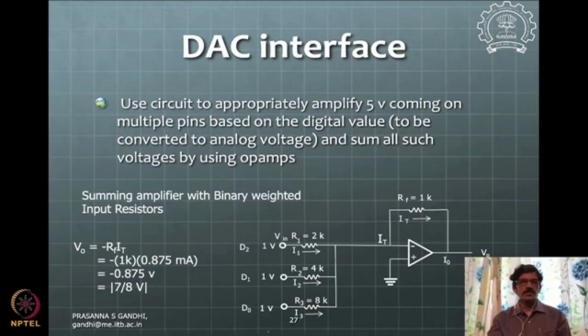Okay, and this is not very wide, but in some applications where you have a motor which you want to run, and it has an amplifier which is an analog to analog kind of conversion amplifier, there you will need a digital to analog interface. Otherwise, typically for running a motor we use a PWM kind of interface, which we'll see.